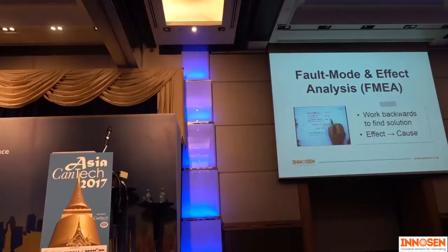The process that I described was that you take a sample, you measure, you make corrections, you start again. Now, that works, and that works quite well to a certain degree. But just imagine that your problem is with double sheets. It's your coating line. It results in sheets that are not coated every now and then. You get customer complaints.